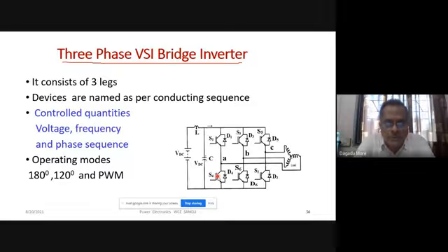The name of this circuit is the commutation circuit. So we require one separate circuit for turning on and one separate circuit for commutation. But the commutation circuit is bulky. It has to carry the load current, and it has L and C components, and that's why the commutation circuit is bulky. Whereas the thyristor's switching frequency is also low.